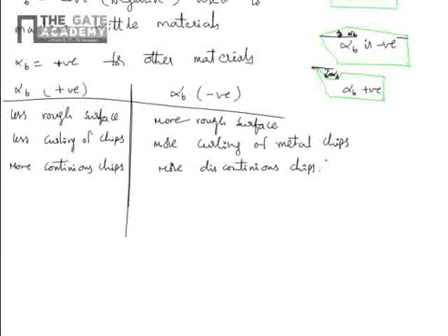And in negative back rake angle, the chip is highly distorted, that forces increase tool vibration and chatter.